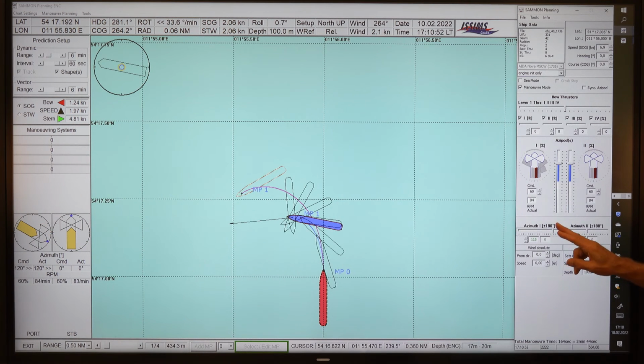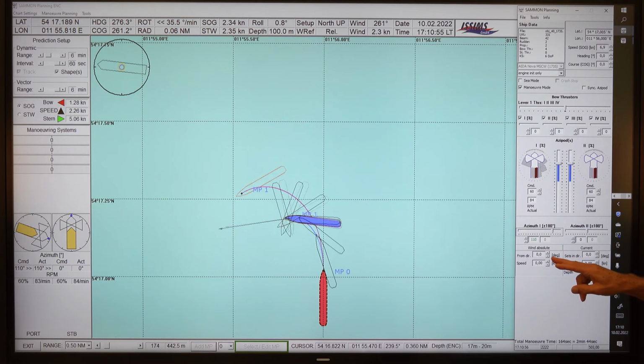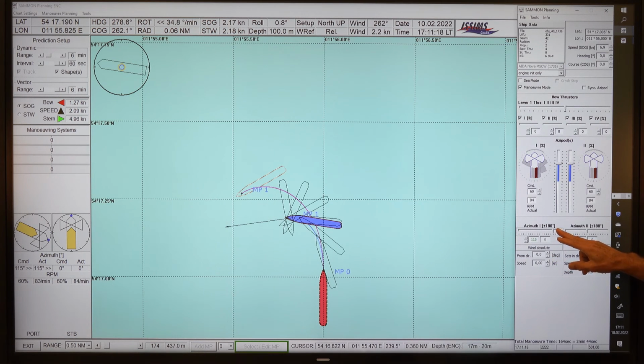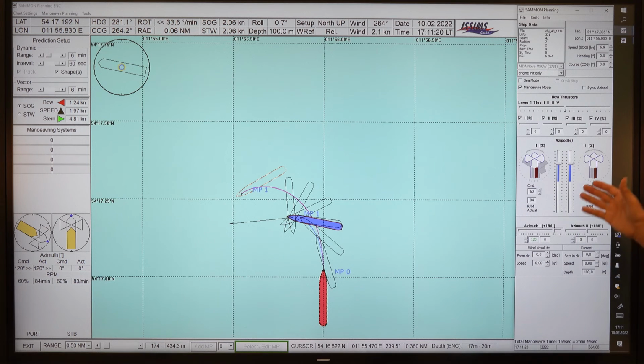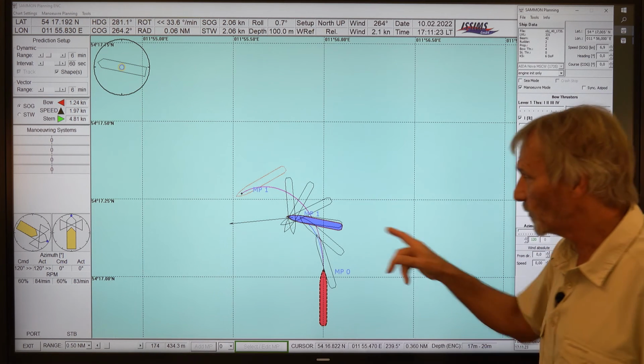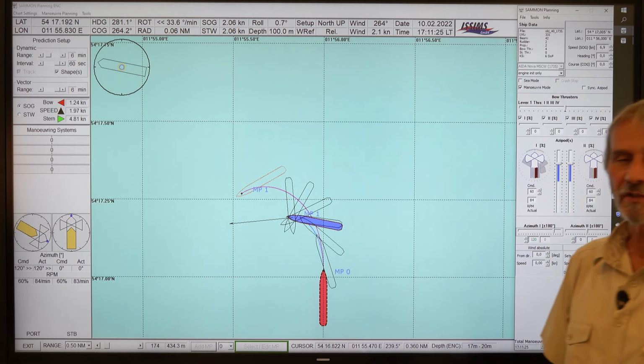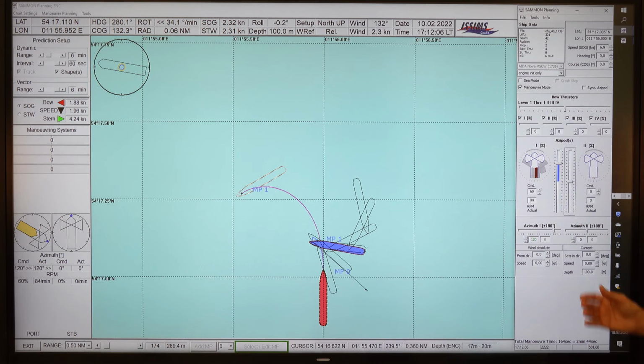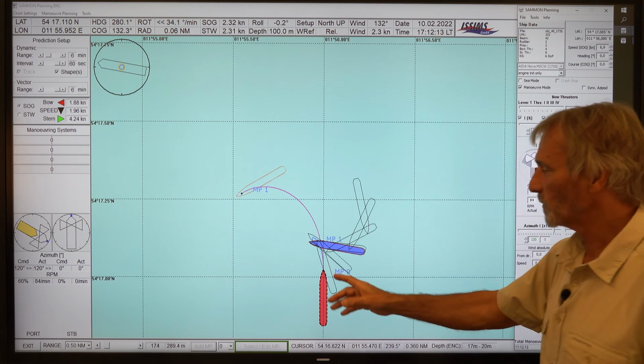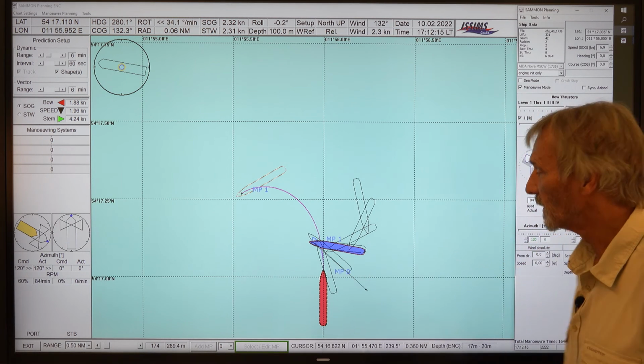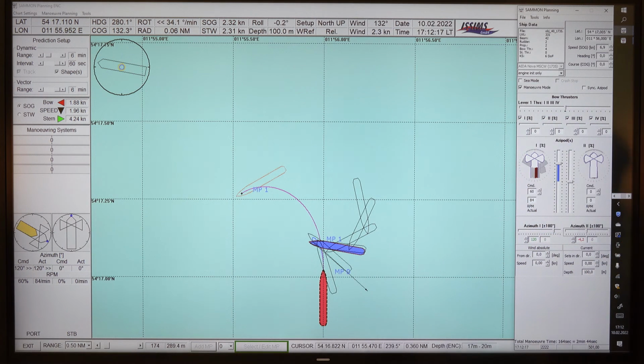So if we play a little bit around with the pots here, if we go to 120, we see that the ship is, with the resulting pot angle of 60 degrees, coming to a halt in this position. This is a maneuver, a kick turn on one engine with 120, so the ship really comes to a stop nearly here, and the other one is set to 0 thrust and zero angle.